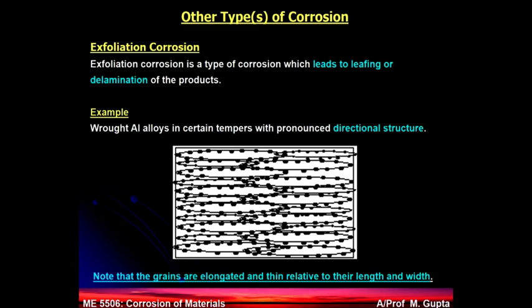Now once you have a precipitate at the grain boundary and you have the inside of the grain, which is white, and a precipitate here, so they make galvanic cells. And when they make a galvanic cell, if it is exposed to the wet environment, the corrosion starts. And the corrosion starts near all these black dots here, because they are the ones making a galvanic cell with the surrounding matrix, which is in dominance. So the corrosion takes place along the grain boundaries, which are long now.